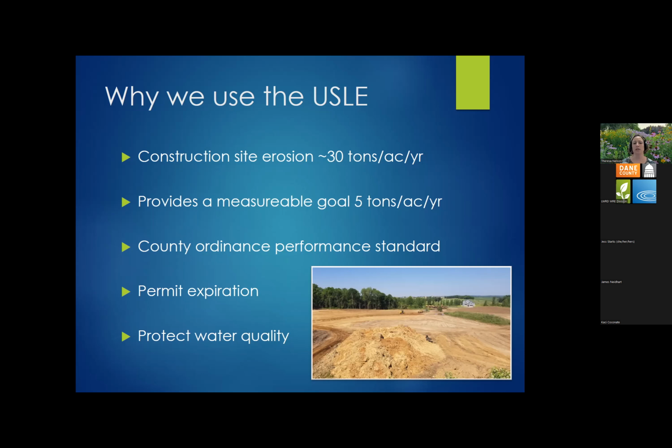Like I said, this is written into our county ordinance as a performance standard that must be met for all erosion control permitted projects. We do use the dates that are listed in the USLE for our permit expiration. When in the USLE the date for restoration is specified, there will be no more soil erosion after that. That's the date that we use for the expiration of our erosion control permits. Ultimately, we use this so that we can protect downstream water quality.